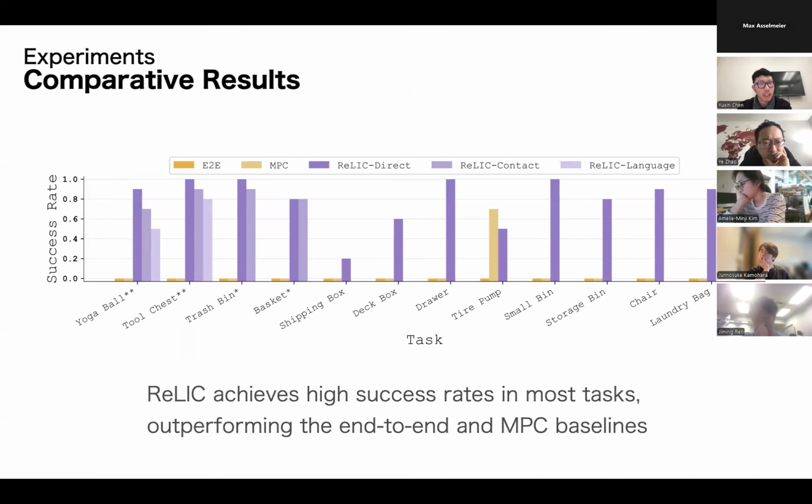We do some baseline comparison because all these tasks we chose for this project involve multi-limb coordination. As I mentioned previously, it's really hard to train an end-to-end reinforcement learning policy, because if we focus more on the stability of the locomotion, then it will sacrifice the accuracy of the manipulation. It simply can't reach the object as well as possible.